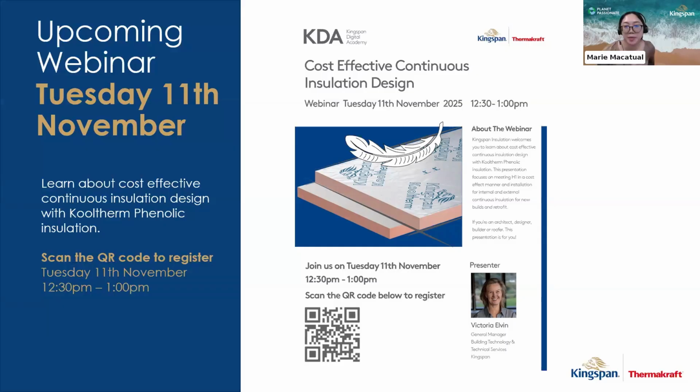Marie. First question, what are the weight limitations when adding a tapered insulation system to a DD400 roof? That would depend on what the structure is underneath that DD400 and the span and so on. So any retrofit system for a roof, we need to be able to look at the structure and understand what is the structure of that roof, and then looking at the elements that are going on top.